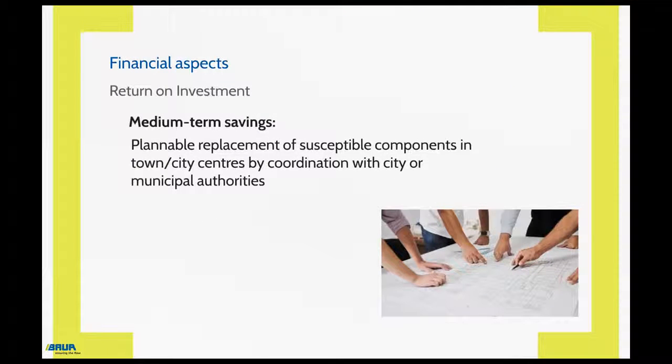Evaluating the condition of cable routes makes it possible to strategically plan for maintenance projects. For example, if a weak spot is detected, the repair can be scheduled for the next time excavation is necessary in this area. If this is not discovered in time and subsequently leads to a fault, an additional excavation must be commissioned, which can be complex and expensive, especially in an urban area. The savings in such a case are at least 10,000 euros.